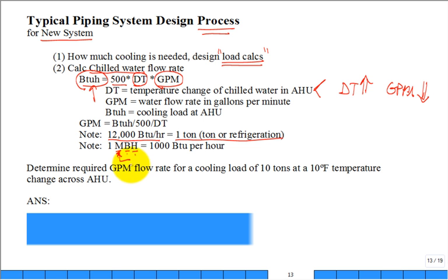Anyway, I think that goes back to, and I may be wrong because I can't remember my Roman numerals, but it's 1,000 BTUs per hour. Now, there's a few people that'll say M BTU per hour, and they'll say, oh, that's 1 million. So be careful. You could easily be 1,000 off. It's not like M means the same to everybody. But the vast majority, that M is 1,000.